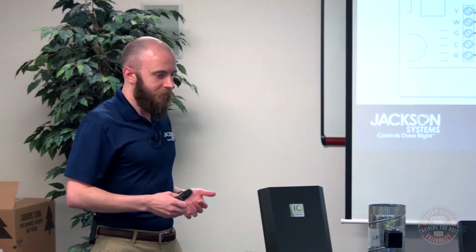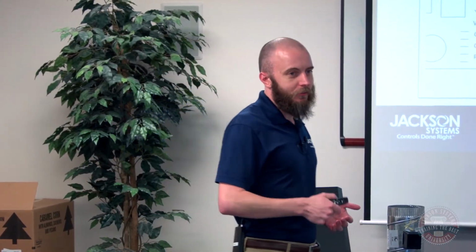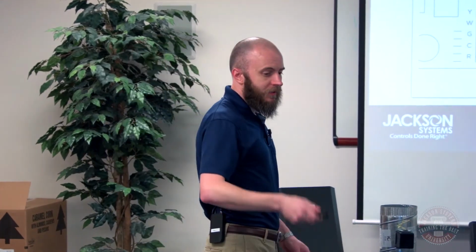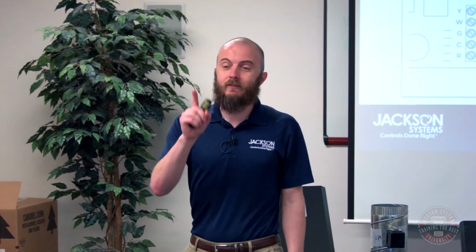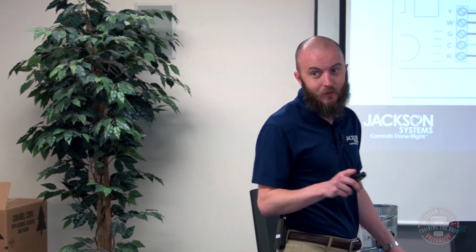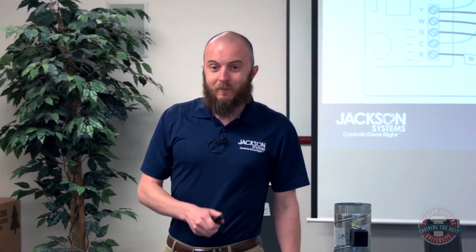Tag your wires. This is something that's probably seldom done, but is always recommended, and can save a lot of trouble down the line when you're pulling wire, when you're replacing systems or whatever. Tag your wires. Don't ever assume that the color of that wire tells you what it's connected to on the other end of that wire. All right? Just because it's a green wire doesn't mean it's connected to a G somewhere on the other end, unless you check it. You have to see it.